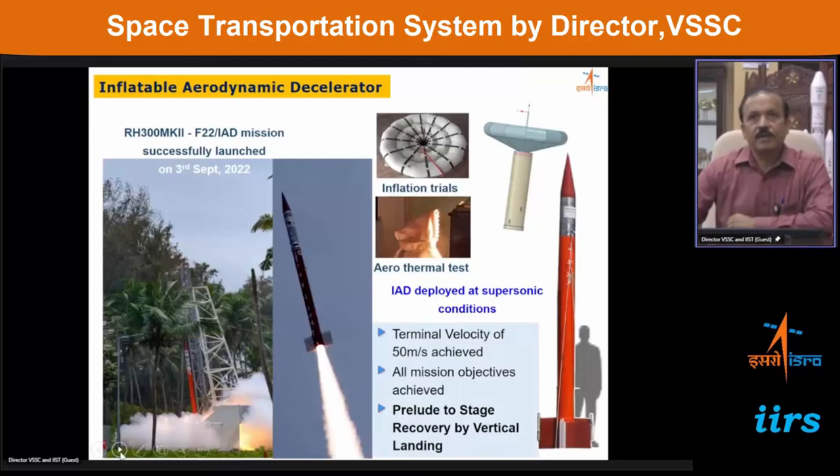We have done one test using a sounding rocket, where it was folded and kept and launched, and then at 80 kilometers we inflated it. By that time the vehicle had gone to supersonic condition, and while coming down from supersonic to low subsonic, the velocity was reduced by the aerodynamic drag. So this is again a concept demonstration. We wanted to see where this can be used in recovering a real launch vehicle stage.